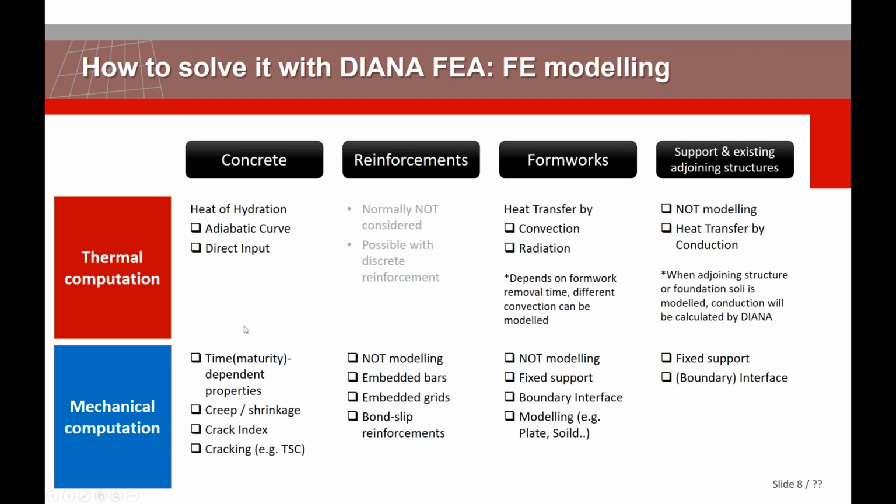And these time- and maturity-dependent properties, creep, shrinkage, and cracking, you can consider as aspects of your concrete. And reinforcement, maybe you don't model it, or if you want to, you can take advantage of our embedded reinforcement, embedded bars, grid, and bond-slip reinforcement.